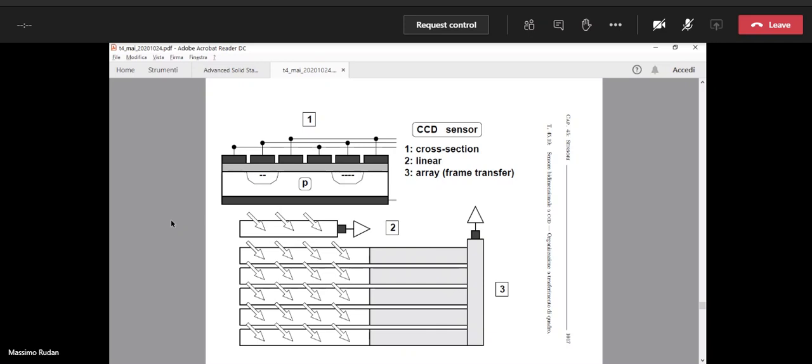Typically, video screens or computer screens are scanned row by row. But there is another format that is also possible, that is called the interlaced format, in which the rows of odd index, number 1, number 3, etc., are scanned first, and then this is followed by the scanning of the even index rows, okay?